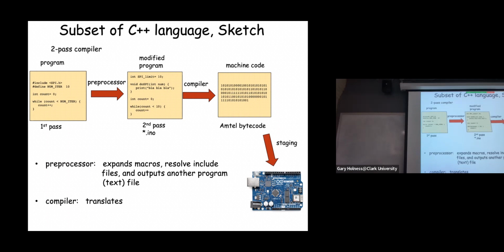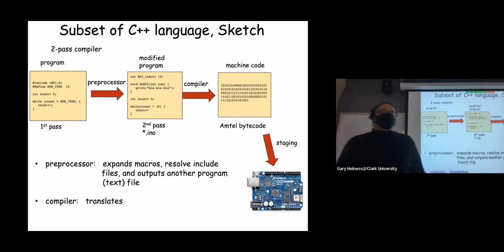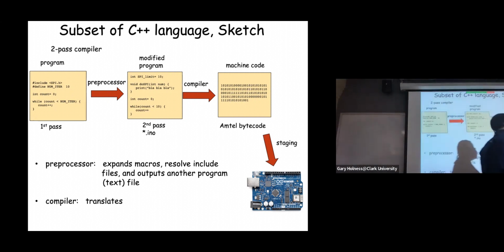The other type of preprocessor command that you'd be using is number sign define. With this number sign define, you see number sign define, space, some string, space, and some other value. It could be a value, it could be another string. What number sign define is, sometimes that's called, excuse me, a preprocessor macro. That's going to cause a replacement to happen.